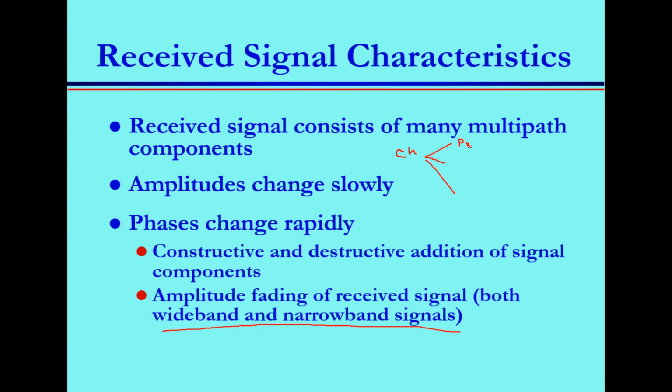If the duration of the delay spread is much less than the duration of your impulse, then you have narrowband. Narrowband means all your signals, all your multipath reflections reach the receiver at the same time. And what does this cause? Fading, amplitude fading, yes? So basically narrowband has a relationship with fading. Wideband, all these, we'll understand in the next lecture how this happens.